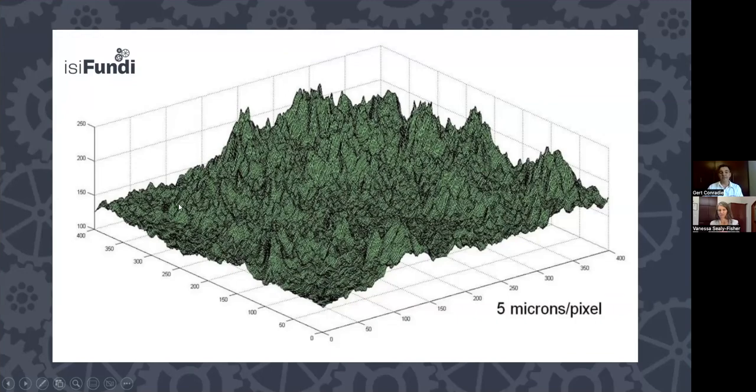And what we have done, and the reason for doing it, and getting to explain the anchor profile, is if you look at this 250 micron pixel representation that you see here, if you've got a string of line all across these peaks and valleys, you have effectively tripled or maybe quadrupled the surface area.